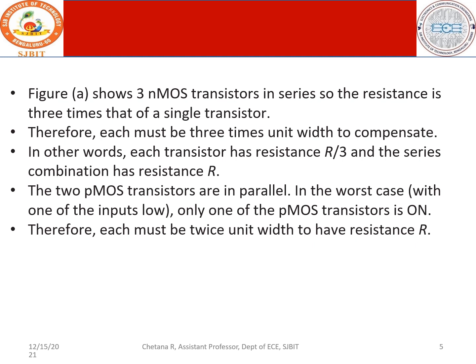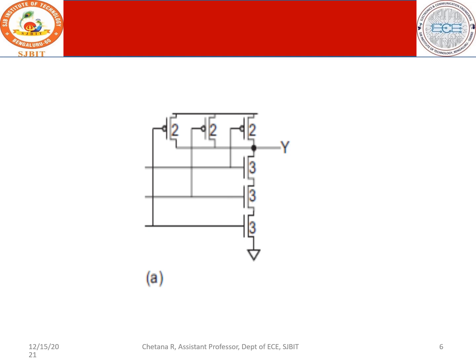It shows 3 NMOS transistors. To construct a NAND gate, we consider NMOS transistors in series. We have already seen a 2 input NAND gate. So NMOS is in series, PMOS is in parallel. Therefore we get the resistances as well as the capacitances. Along with that we can go along with the diagram. So this is a 3 input NAND gate.